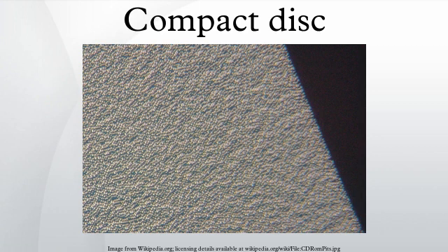To prepare to press a CD, a glass master is made, using a high-powered laser on a device similar to a CD writer. The glass master is a positive image of the desired CD surface. After testing, it is used to make a die by pressing it against a metal disc. The die is a negative image of the glass master. Typically, several are made, depending on the number of pressing mills that are to make the CD. The die then goes into a press and the physical image is transferred to the blank CD, leaving a final positive image on the disc.